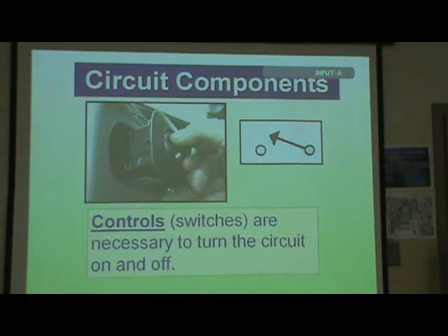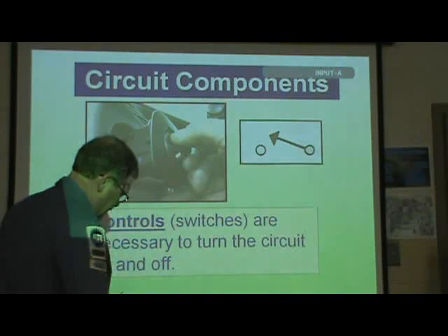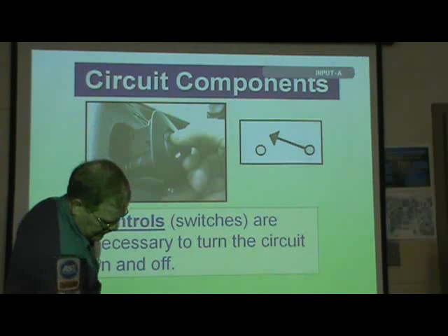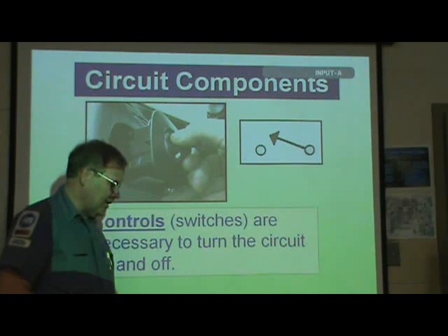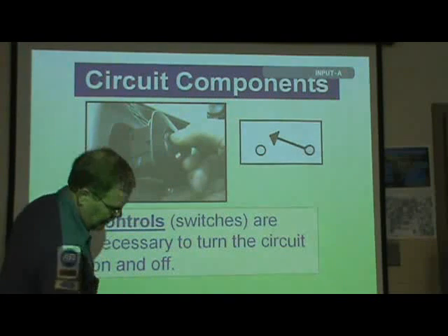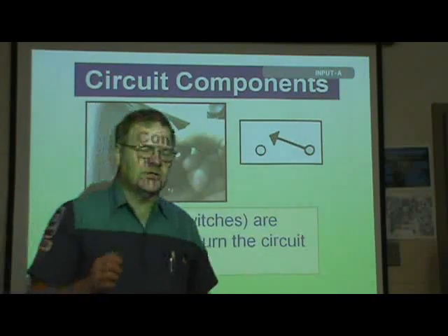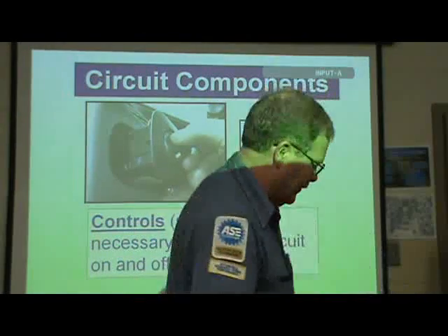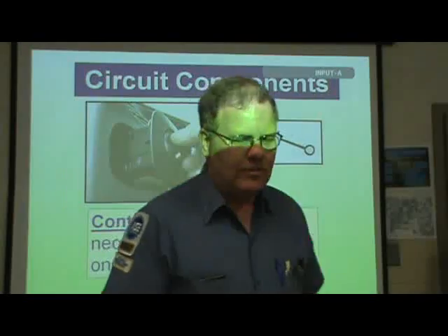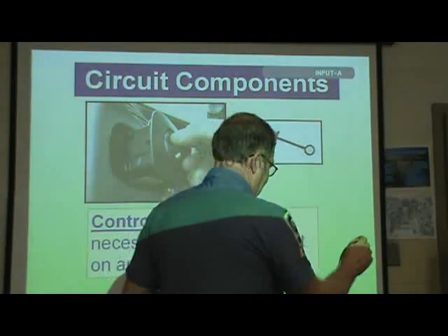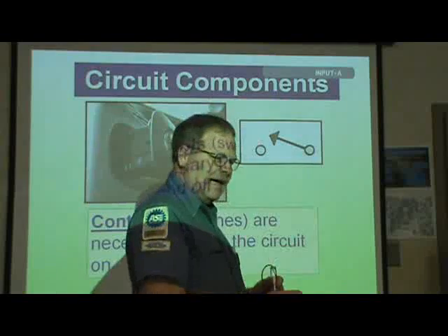Okay, let me ask you this. What if I take my test light out here? I hook it to the battery, and if this thing right here was hooked up to power, and I hook this to ground, and I touch this big wire coming from the alternator, it should be hot. Right? Okay, so let's say that I go to start the car, and it doesn't do anything. They say, we've already replaced the battery with a brand new battery, and it still doesn't do anything. So I get my test light out and I hook it from here to the other side of the battery, and it lights up really good.